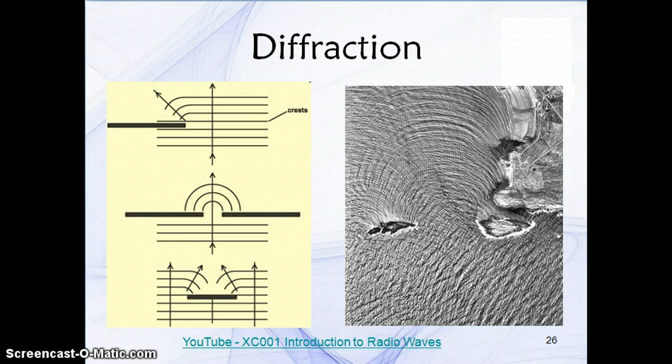And scattering. The wave encounters one or more objects, a fraction of the size of the wavelength. The wave becomes fragmented and bounces over wide angles. This occurs more often at higher frequencies, VHF and above. Similar to scattering of a light beam when shone into a fog or mist, and tropospheric scatter, regularly used with higher power transmitting equipment.